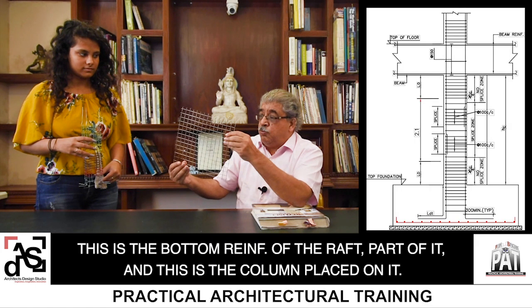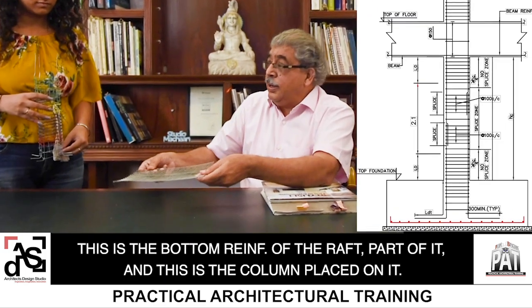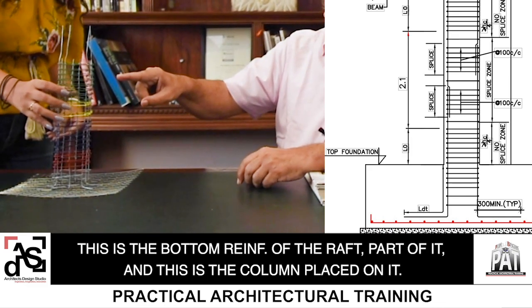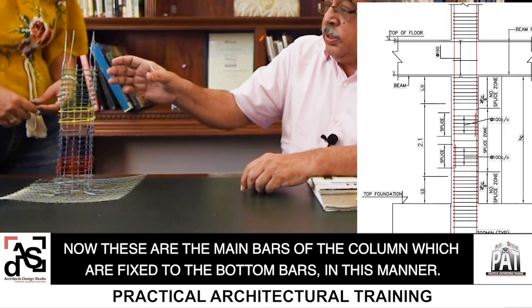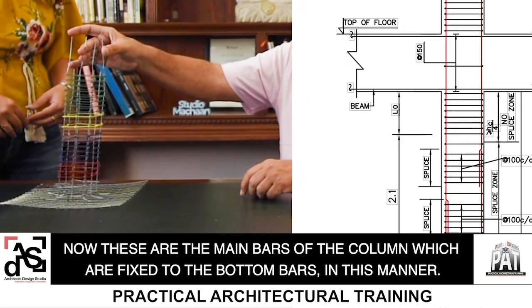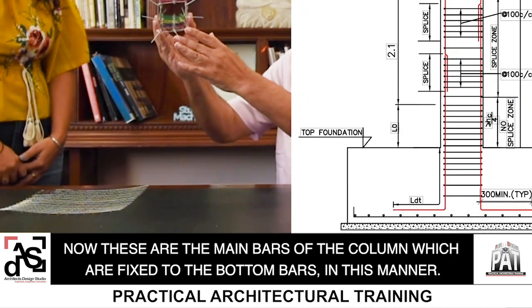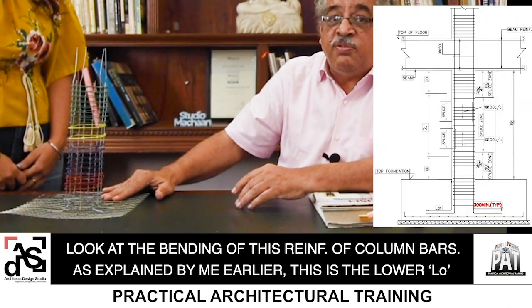This is the bottom reinforcement of the raft, part of it, and this is the column placed on it. Now these are the main bars of the column which are fixed to the bottom in this manner. They are fixed to the bottom reinforcement of the raft.